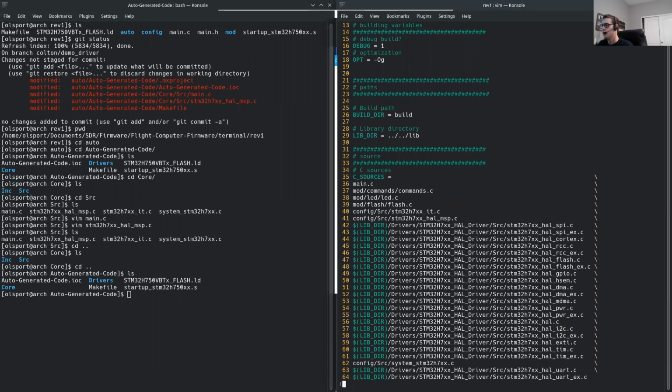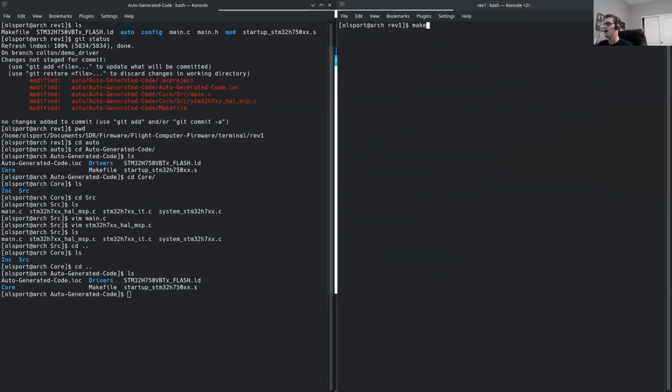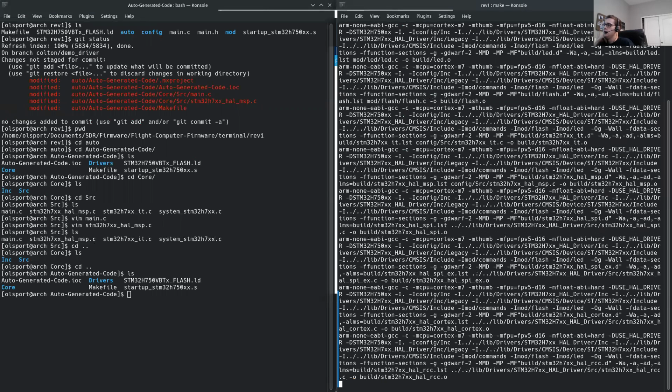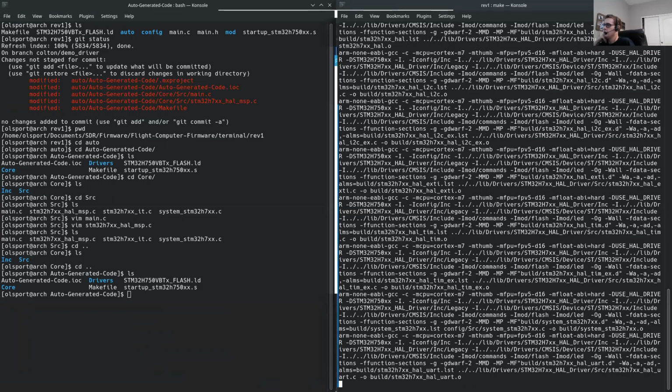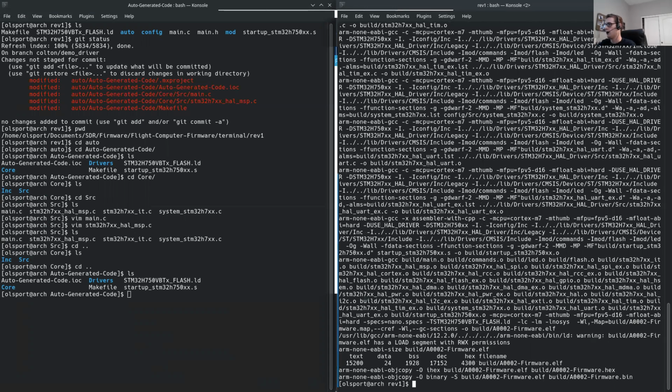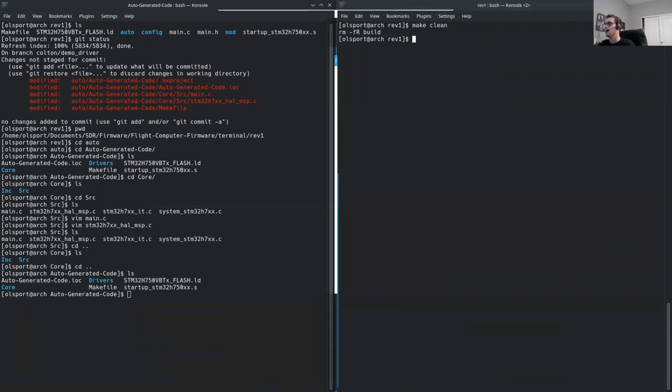So the only thing left to do now is to compile it and make sure it compiles without error. So we'll just run that compiler there and things are looking good. No errors or warnings. So that means we're good to go. At that point, our microcontroller is now properly configured to be able to do I2C stuff. From this point, it would just be actually working on the driver functions and using those I2C HAL functions to do that. So that's about it.